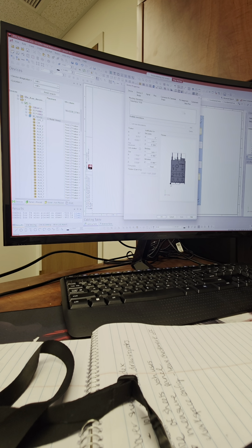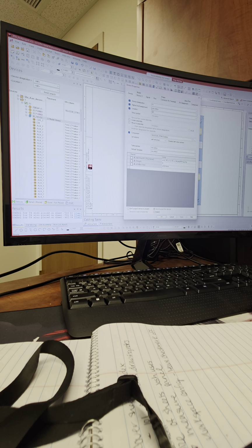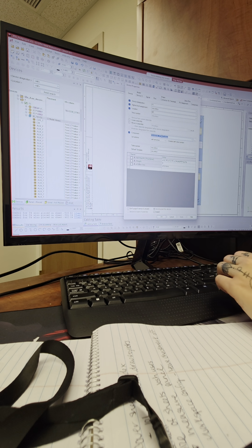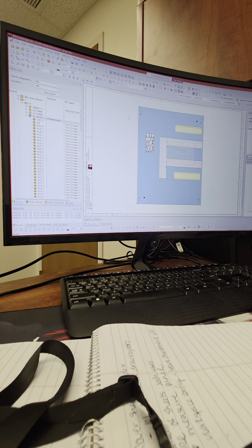To do this quick fix once, click on the Device tab just to grab the part number for this part, so we can delve into it. Under Component, copy that entire 193 number. Okay, Control C, copy it. Cancel out of this. Now we're going to go into our library under Component and search for the component name by just pasting it in there. Press Enter.